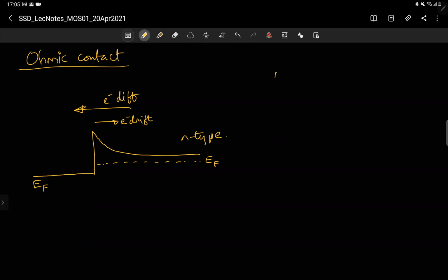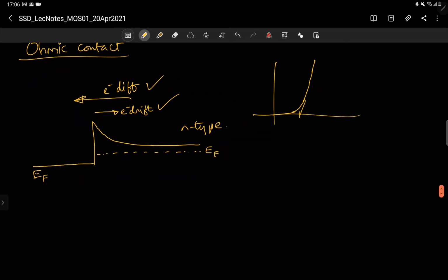Which means if only these two mechanisms are there, I will always find characteristics with almost zero current, because diffusion has not become strong enough and drift is still there. Only when drift becomes very small, because the applied bias cancels the built-in field, which happens at the cut-in voltage, does it start rising significantly, because drift has almost died and only diffusion is seen.